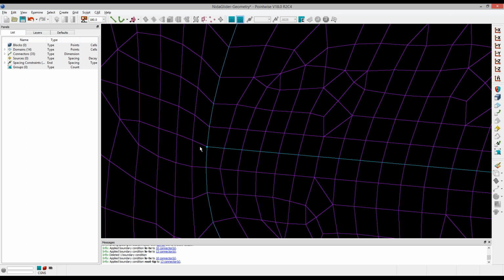And that's because low area ratios means that the cell sizes are all roughly equivalent to each other in their local vicinity. So smaller elements on the surface, when you advance those into the volume, are actually going to stop sooner. They're going to reach an isotropic or uniform state sooner than larger elements. So if you had large area ratios, you'd have a small element directly next to, say, a large element. Well, that small element, as it advances, will stop sooner in fewer layers than that large element. And that could actually influence the growth of that larger element.